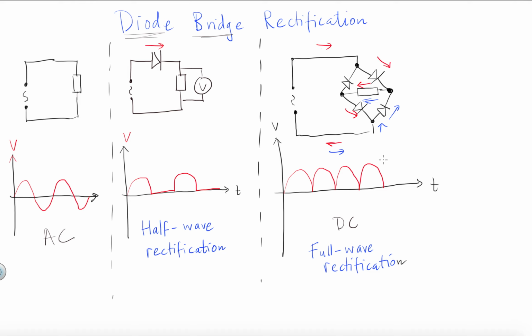So this is what we call a diode bridge, and you end up seeing the full wave rectification, but it does actually go down to 0 at certain points, and the way you overcome that is by using something called a capacitor connected in parallel to the resistor, and the concept of capacitance we're going to come on to in a later stage. But basically, to either end of these junctions, you take wires away and you join in something called a capacitor, which is a store of charge.